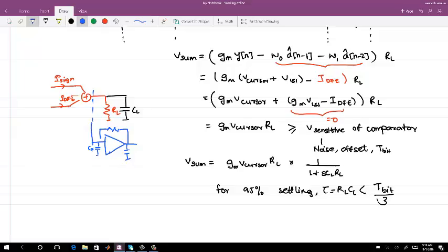That will come later. But putting a specific amplifier between the comparator and the summing node is going to add delay. You need to be cautious. In some applications it may turn out to be the better thing to do, but it may not be as the speed increases, because of the delay.